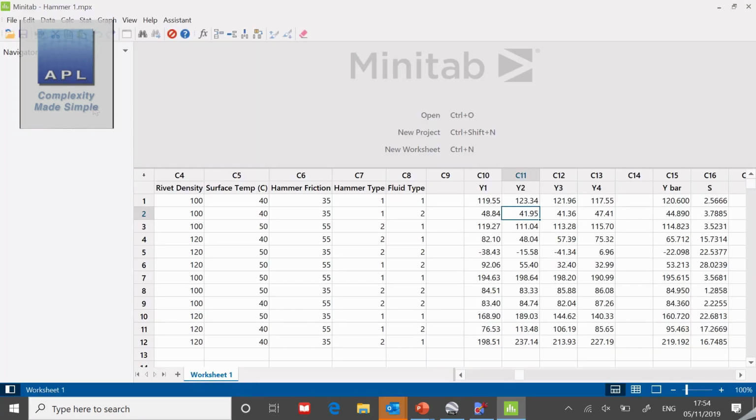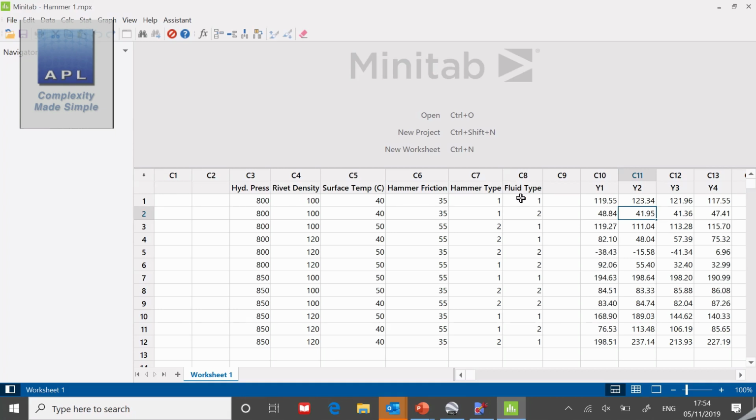Now to save time, I've already got the DOE and the data into a Minitab worksheet. You can see, just scroll it across, you can see the 6 variables, you can see the data. It's all in a table, you'll notice. It's not down in a column like Minitab would normally do this, because this is a Taguchi design. And besides, I like to be able to look across the row here. This is really important to me. I like to be able to see that I've got some consistency across the rows. So I really want the data to be in tables. So here is the L12. It's all set up for me to do some analysis.